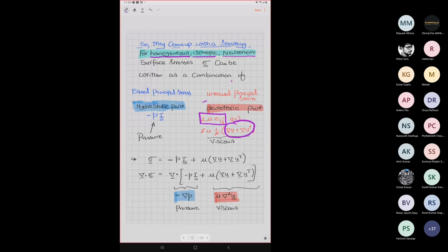may not be easy. It might be a combination of different things, but you pretend that it has the same density. Such approximations are very useful for mass. And if we do it for thermophysical properties, we call it homogeneous. Based on space, you take any space, the same kind of properties you are supposed to approximate. Immaterial of direction, we call it isotropic.